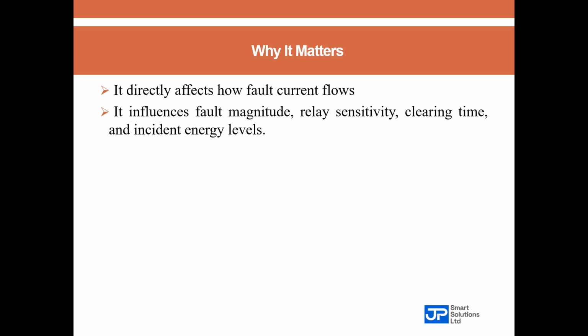So, for example, a solidly grounded system will produce a large ground fault current. A high resistance grounded system will limit that current drastically, but it also affects the relay pickup settings. So ignoring these differences means that your relay coordination might look perfect on paper. It may look perfect on your simulation, but in the field, it will fail.